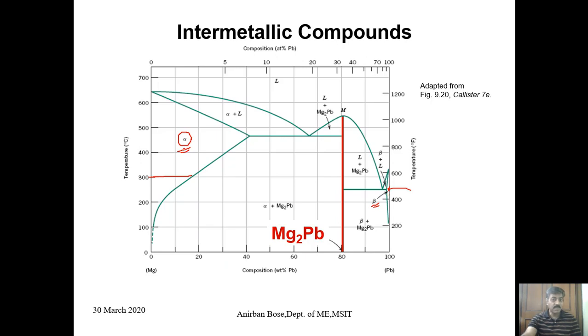Okay, what are the other primary phases present? That is the liquid. At very high temperature above the melting points, in this region, you can see at liquid state they form a single phase. So how many primary phases can we see in the magnesium and lead diagram? This binary system has alpha, which is one solid phase that is magnesium rich, the liquid, and beta, another one which is the lead rich phase. So what we have observed is that magnesium and lead both have limited solubility in one another, and that is why this kind of phases are created.